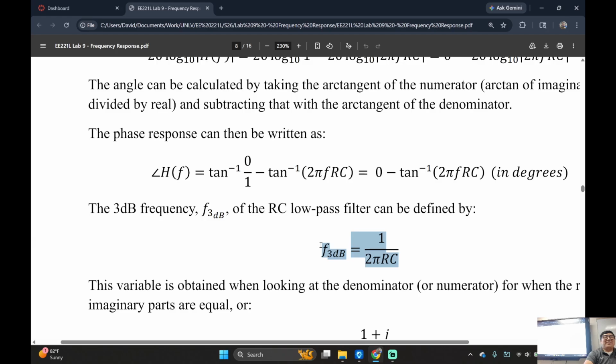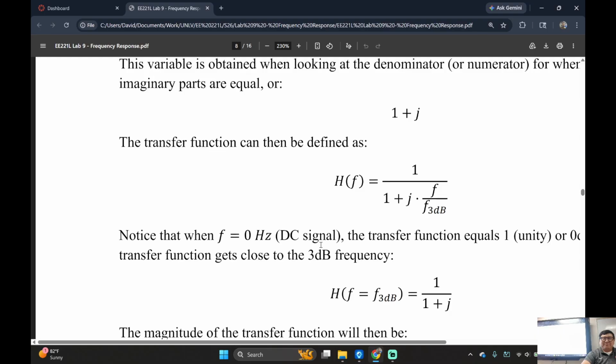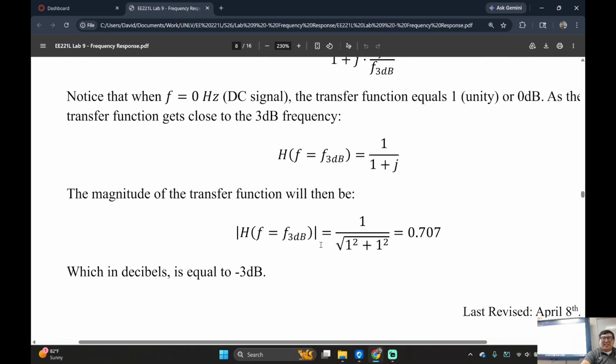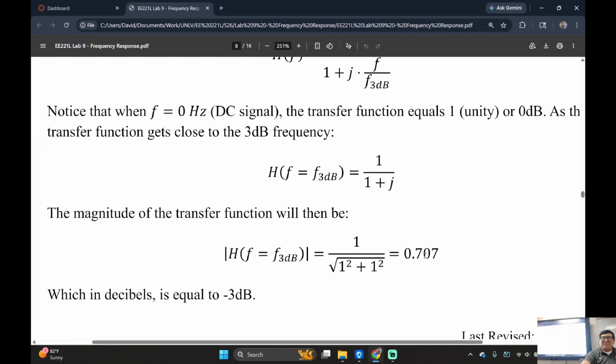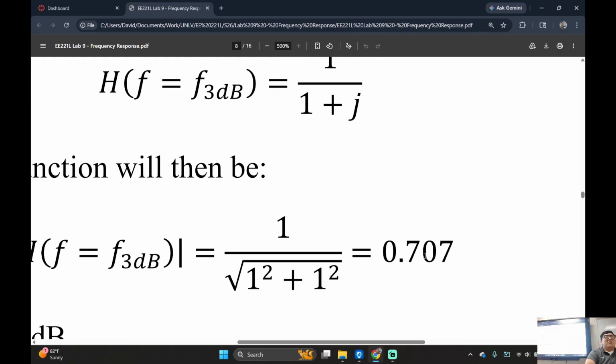What's bandwidth? It's just the width of the band, right? Just how long it is. And then here's a good number, 0.707, or LOL upside down, right? So this is your favorite magic number. What's the 20 log dB of 0.707? Minus 3 dB. All right, these are two numbers I want you guys memorizing for the rest of your lives.